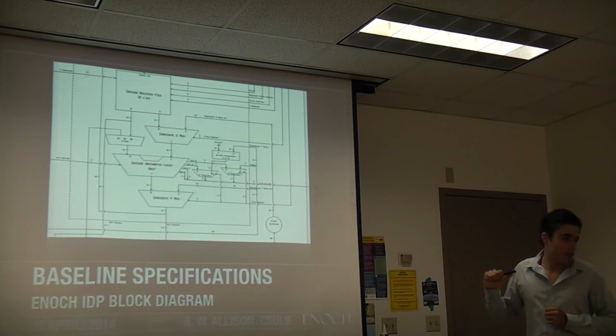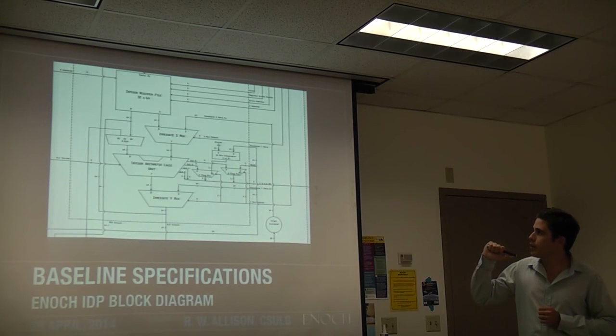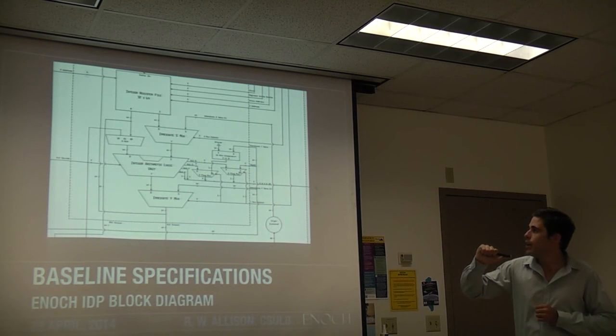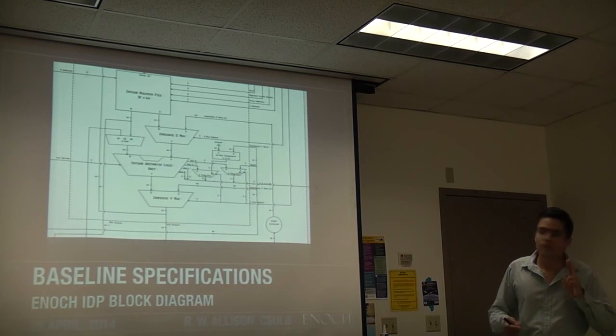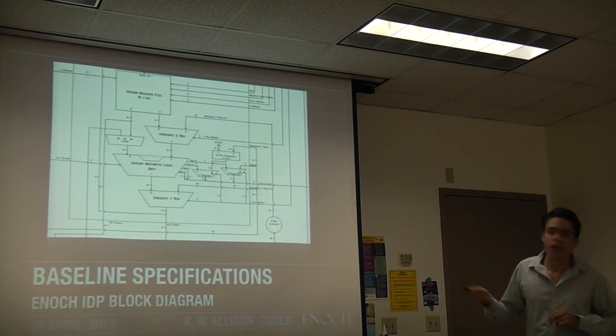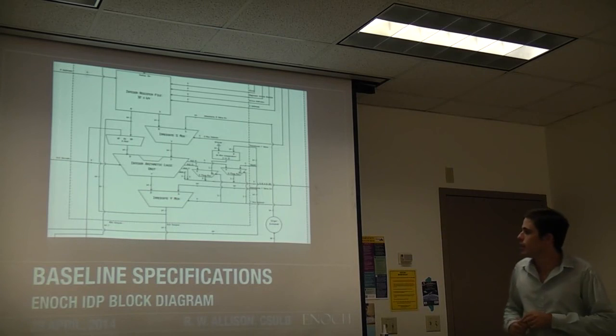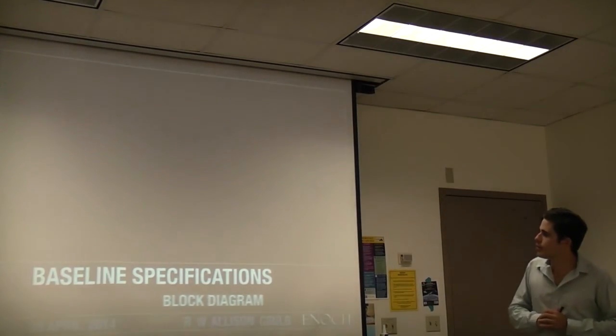Also, to check the negative immediate values, we chop off the highest MSB of that immediate value, and then we put this in our N flag MUX, which either takes in the ALU N or that immediate value into our flags. Now you can't overflow on immediate loading, and you can't get a carry either, but you definitely can get 0 or negative. So we're going to go further on to the next.